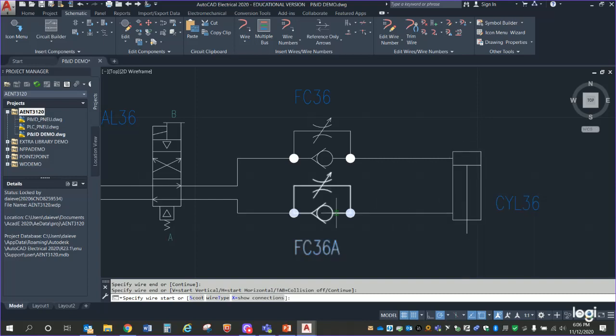As it's returning, can it go through the check valve? Why not? I'm pressing that ball into the seat, right? I'm not pushing the ball off the seat. I'm pressing it into that V. It's not allowing flow. So which way does air have to go? Through the restricting orifice and back.